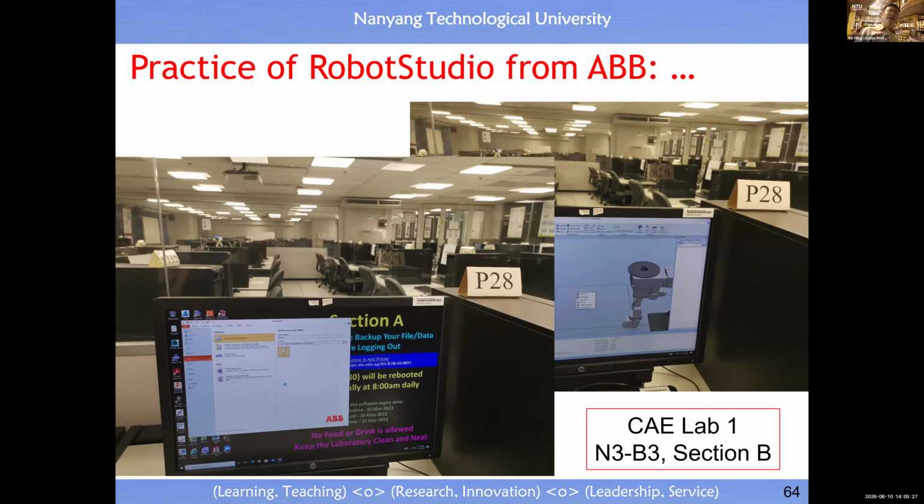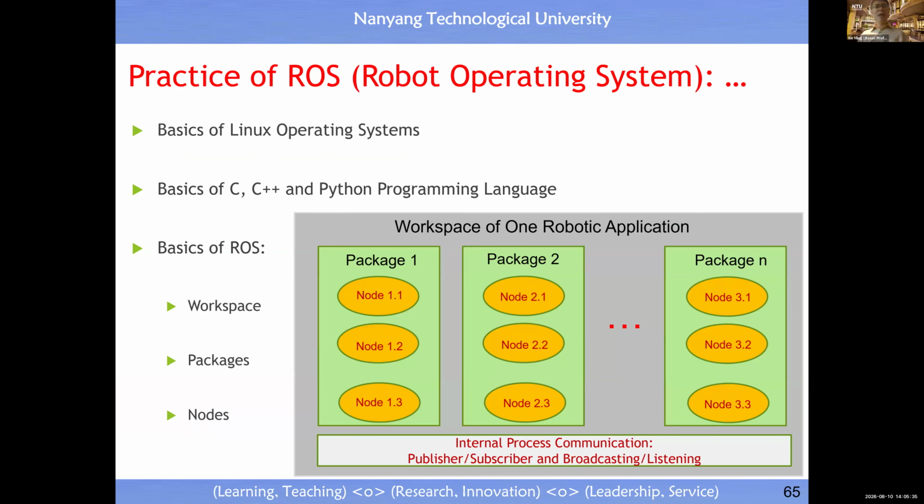Amma will be in charge of guiding you with experiments and hands-on practice. You may also have heard of ROS. ROS is free. This slide gives you a little bit of guidance. ROS is a library that helps you easily establish intermodule communication. You must follow the terminology of ROS, such as package, node and application. Inside an application, you have a lot of packages. Inside a package, you have a lot of nodes. Then how to communicate amongst the nodes or modules?